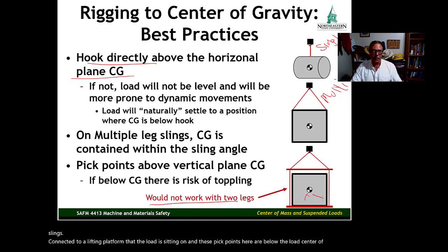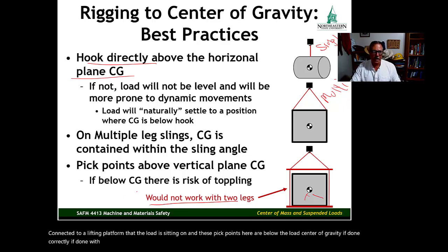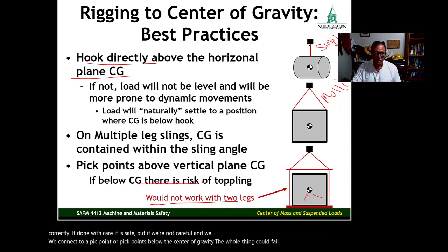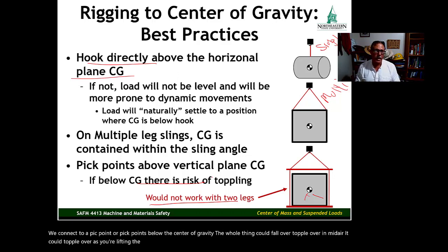If done correctly, if done with care, it is safe. But if we're not careful and we connect to a pick point or pick points below the center of gravity, the whole thing could topple over in midair. It could topple over as you're lifting the load. You may not even get it into the air, depending on some different variables that may be at work in the situation.